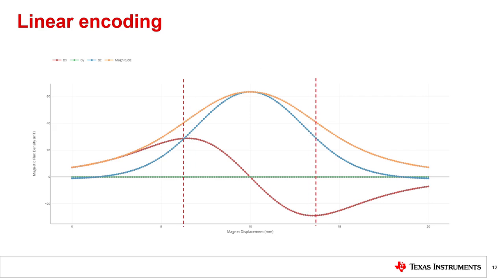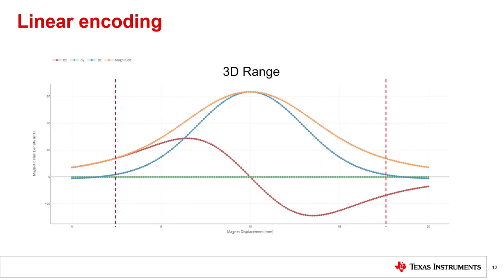However, there is still more magnetic field data that could be used by a three-dimensional sensor to expand the sensing range. When using the full magnetic field, angle calculations can be used to determine a much wider stroke length. The challenge here, though, is that an unadjusted arctangent measurement will be quite nonlinear, so this method often requires characterization to reach the best overall accuracy.